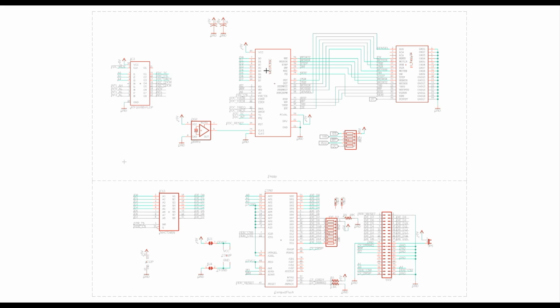Now, I ran out of room in the PLD. In the SBC 188, they were able to fit all of their I/O decoding and other decoding in those two PLDs. But when I went to the 16-bit bus and the extra complexity of the high and low data bytes and all that, I didn't have enough room. So I added a third PLD, which generates these floppy signals. It takes a floppy chip select as well as 3 address lines, and it will turn on the terminal count, the CS, the DMA ACK, the operations register load, and the control register load.